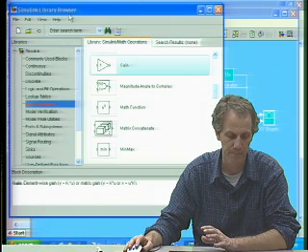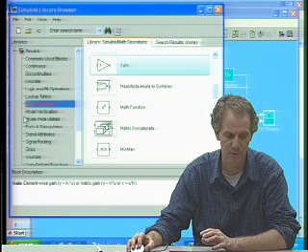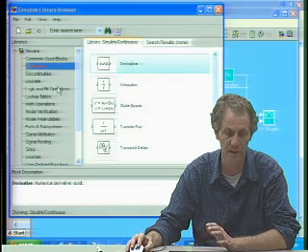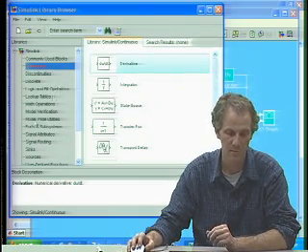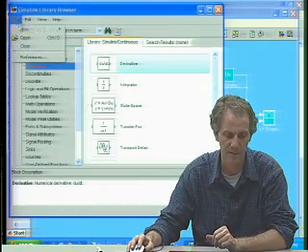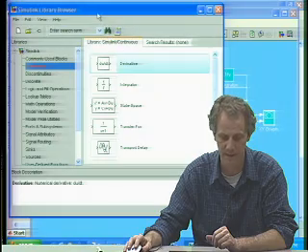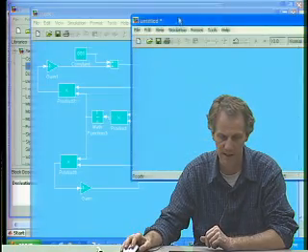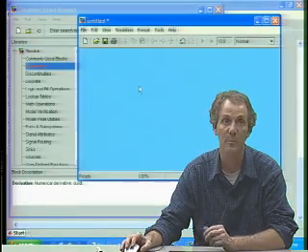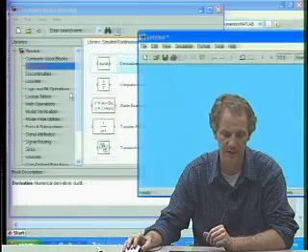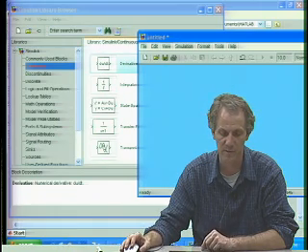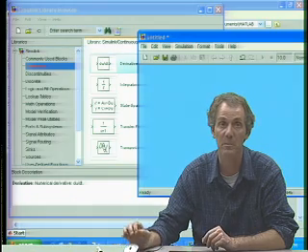And it gives you a list of directories, and you can click on those different directories and different blocks come up to choose from. There's a lot more here than I can go into, but there's a lot of different tools that you can draw with. And then you say File, New, Model, and I already did that, and this blank screen pops up. It's a drawing palette. You're going to take devices from over here, grab them, plop them down into your Simulink diagram, and tell it to do an operation.